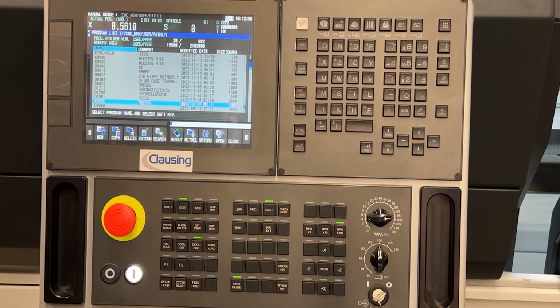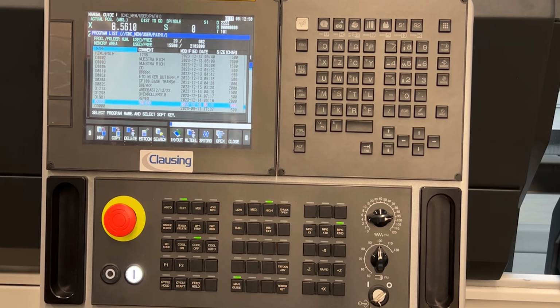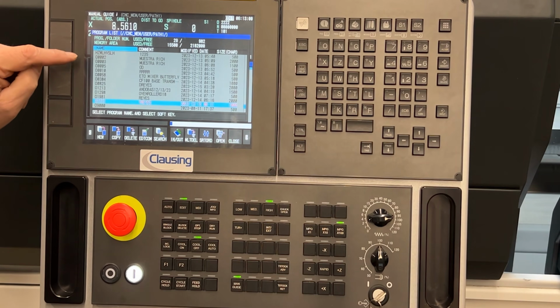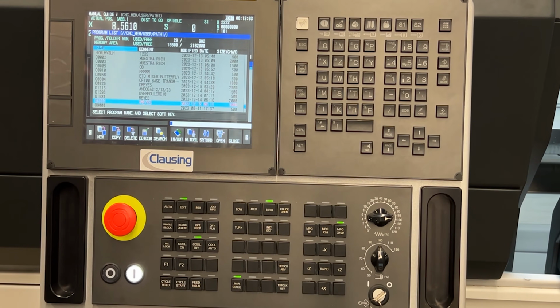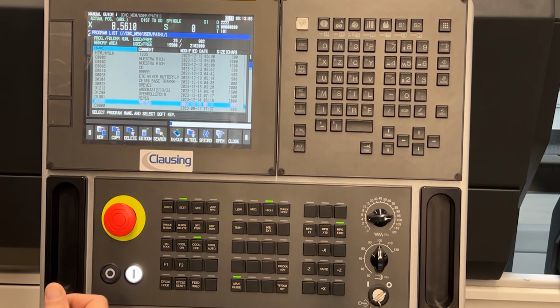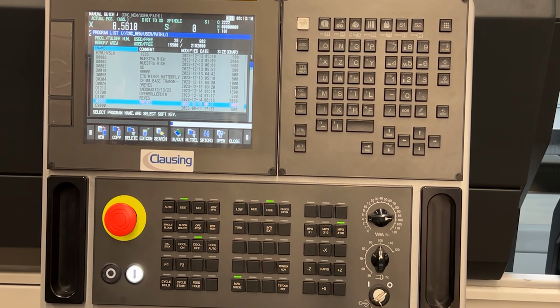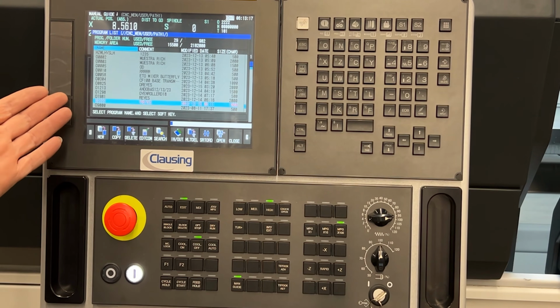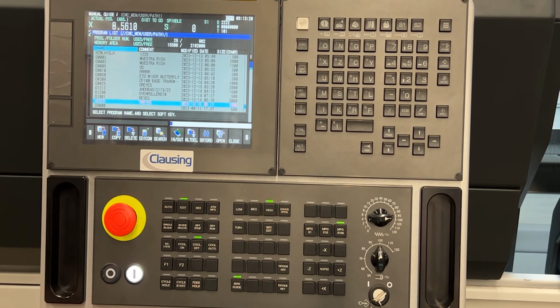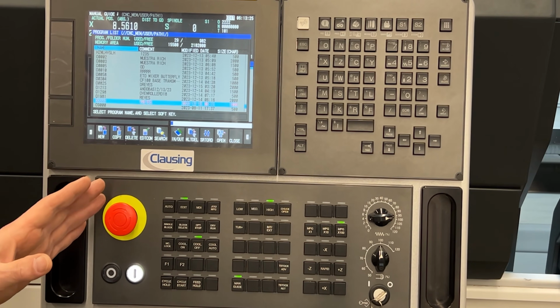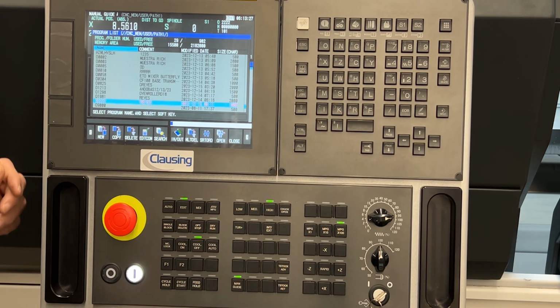We're going to press O list, and then that opens up the window of all the programs that have already been stored. If I want to create a new one, right now O001 is available, and we're going to keep the Fanuc concept of a program number. We can use letters and stuff in the program name. It's just for uploading, downloading on the G-code side, not necessarily Manual Guide i. It's easier to work with just the letter O and then a 4-digit number.